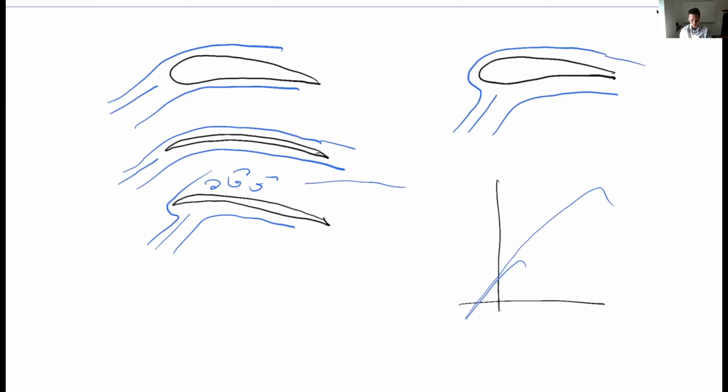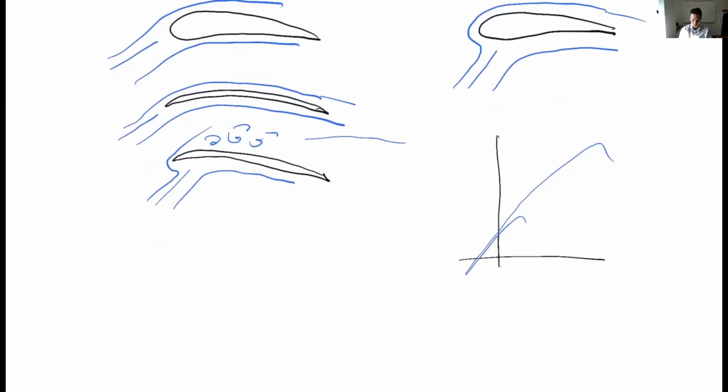Well, what about the streamlined trailing edge? That one is maybe more obvious, but a bit surprising for how important it can be. Now, this is not exactly to scale because I'm freehanding it, but this is about the right perspective. For, say, a large Reynolds number, an airfoil, it's a bit thin, let me redraw that. So an airfoil like this and a cylinder like this, they have the same amount of drag. Again, that's not exactly to scale, but it's not too far off either.